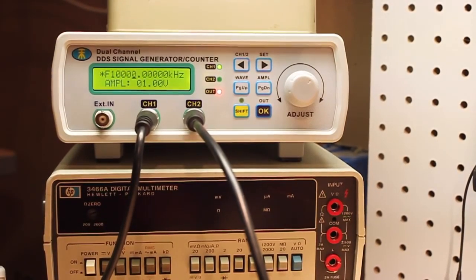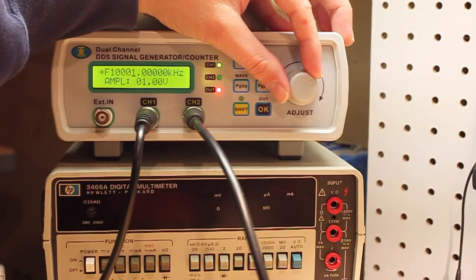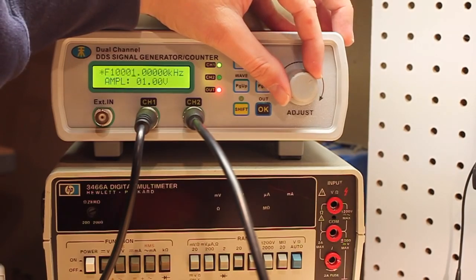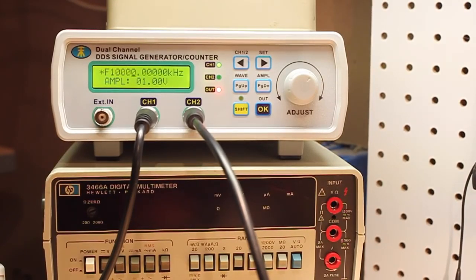So if I move this frequency up by 1 kilohertz, we hear a 1 kilohertz tone. If I move it up by 2 kilohertz, we hear a 2 kilohertz tone. So I can tune, and as I tune, I can hear the 10 megahertz signal on the RF port being down converted to different frequencies. And likewise, if I'm transmitting a signal and you're listening on 10 megahertz, I can change my transmit frequency slightly so that you hear different tones at different times. So that's really just basically frequency modulation.